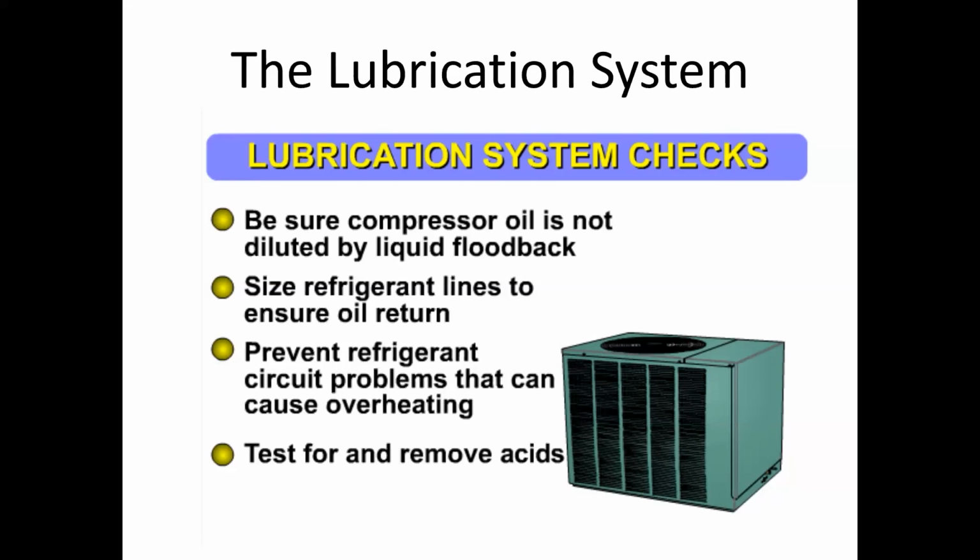Sometimes, depending on where those refrigerant lines are run and how well they're insulated, and sometimes that insulation is due to how old they are and how long that line's been in there, and what the condition of that Armaflex or that insulation on the refrigerant line is. But that lets me know if I have any liquid or not. If you have superheat, you can't have liquid. So we don't want liquid going back into our compressor.